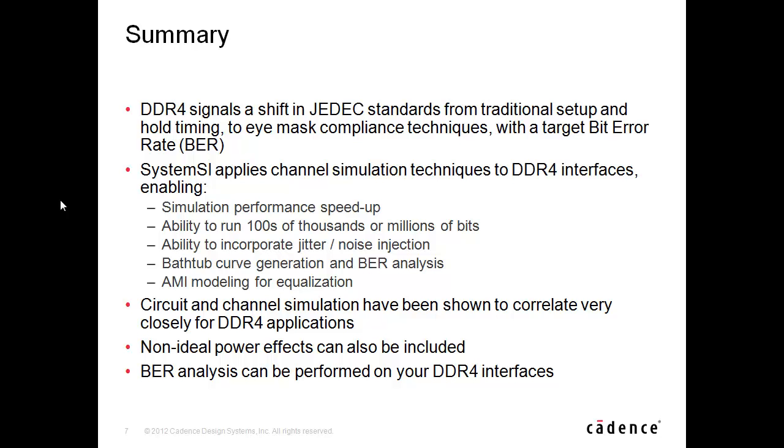This enables efficient jitter and noise injection, as well as bathtub curve generation for BER analysis. IBIS AMI models can also be applied to model controller equalization. Circuit and channel simulations have been shown to correlate very closely for DDR4 applications, including non-ideal power effects. The bottom line is that bit error rate, or BER analysis, can now be automatically performed on your DDR4 interfaces.